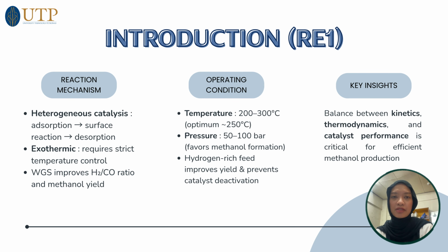Methanol synthesis occurs via heterogeneous catalysis, where reactants are first adsorbed onto the catalyst surface, undergo the reaction, and then desorb as products. The reaction is exothermic, so strict temperature control is essential. The water gas shift reaction helps improve the hydrogen to carbon monoxide ratio, enhancing methanol yield.